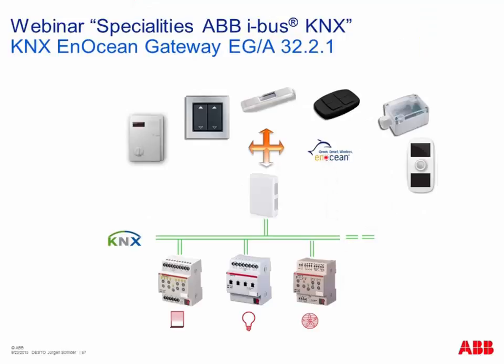So there's also a kind of wireless standard, which is the so-called EnOcean standard. Behind EnOcean there is the EnOcean Alliance. Also a group of manufacturers have joined together and specified here this wireless EnOcean standard. Wireless means that all these devices, for example mainly sensors, motion detectors, magnetic reed contacts, have no battery inside. They're based on energy harvesting.